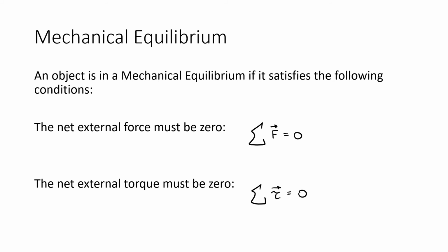But we have this other mass right here. Going from the center of mass, it's this radius away from the pivot point, and it's trying to force it down that way. So we have a torque trying to twist it that way. These two torques sum together to equal 0. And so we have this thing that is balancing.